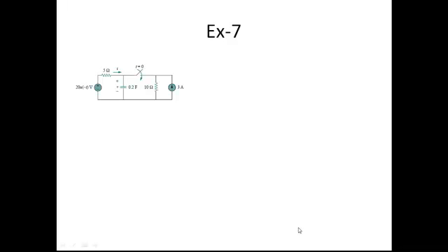Carefully watch this example. You are having a unit step function also. You are having switching also. Okay. So this is an interesting example for you. The switch is closing at time t is equal to 0. Whereas for the unit step function, instead of u of t, now you have u of minus t. I hope you remember what is u of minus t. For time t lesser than 0, it is 1. For time t greater than 0, it is 0. So here also the switching is taking place at time t is equal to 0.